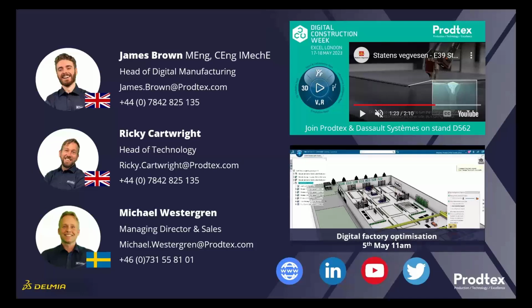I'm not sure if we already mentioned this in the session or not, but the point cloud on the screen there was actually captured just with James's iPhone. There's an area in the building, and James went out with his iPhone and used the LiDAR scanner to capture it. Depending on what you want to use it for, there's much more expensive equipment, or companies will come with that equipment to get you a much more detailed, higher-accuracy point cloud. But if you're just looking for a quick check, a quick first-pass analysis, and you don't need a huge level of accuracy, you can get those point clouds with a relatively cheap piece of hardware like that, right? Exactly.